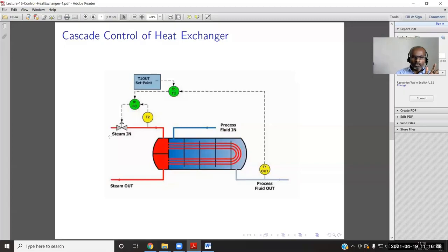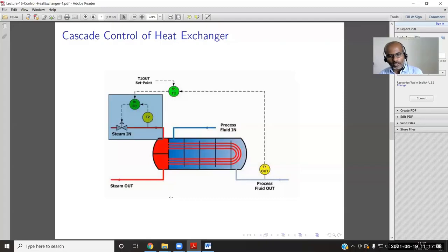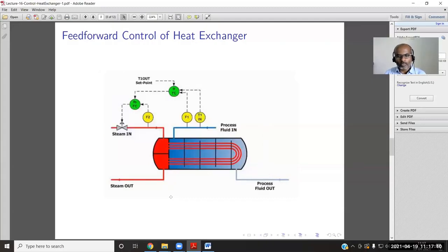One set point, one manipulation, and one output, but many measurements and many controllers. Normally we have 2 measurements and 2 controllers. There can even be one more inner loop as well. Normally the innermost loop is a flow loop, which is a fast response system.